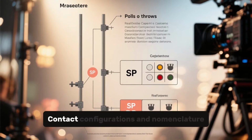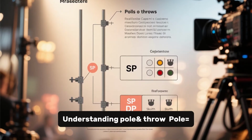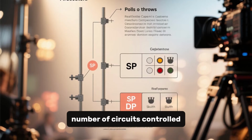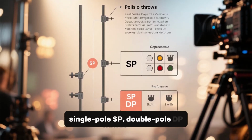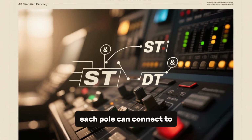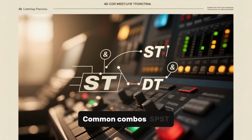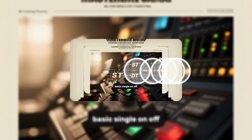Section 7. Contact configurations and nomenclature. Understanding pole and throw. Pole equals the number of circuits controlled: single pole, SP, or double pole, DP. Throw equals the number of positions each pole can connect to: single throw, ST, or double throw, DT. Common combos: SPST, a basic single on-off.